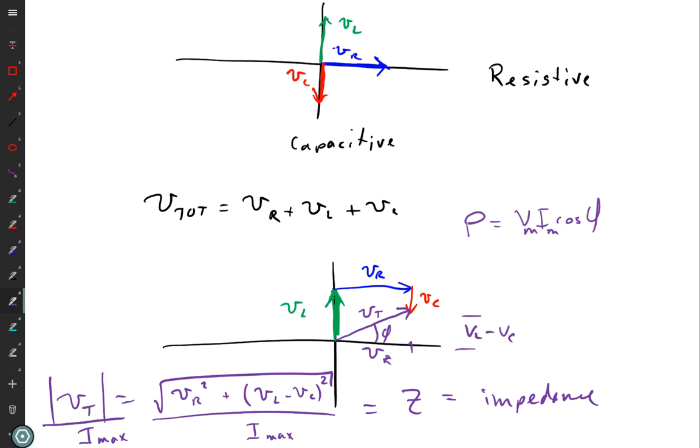So in something like a motor, you have a refrigerator. Refrigerator has an electric pump. Electric pumps are made with a bunch of windings of wire. But what's a winding of wire? It's an inductor. And so that pump is a big inductor. And so when the pump turns on, you have a big inductive load, which means that you're going to have a lot of apparent power that's not actual power.